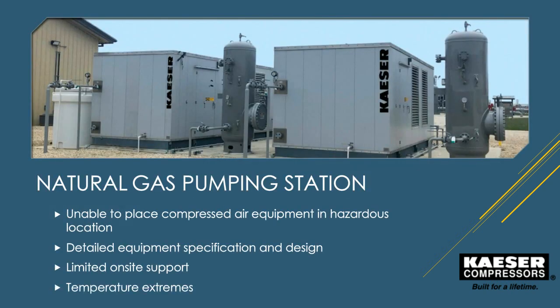There are many applications that involve special locations with different or dangerous requirements. Here's an example of a natural gas pumping station. The compressed air needed to be utilized in the hazardous zone or a class zone. However, with a compressed air package such as this, the package can be placed on the outside or the perimeter of the hazardous location and the compressed air piped in for use.